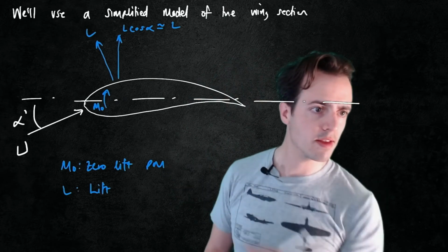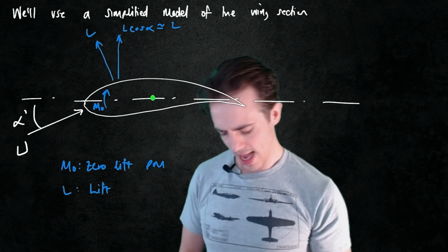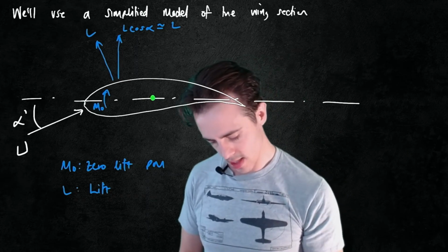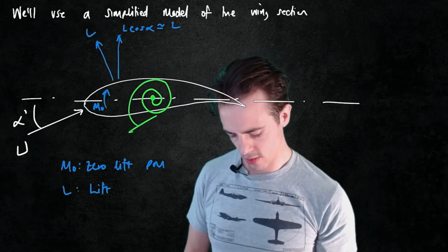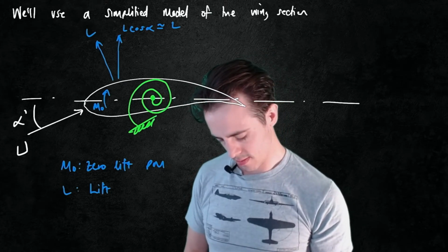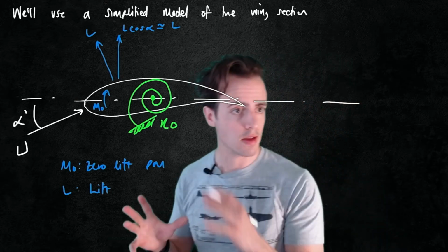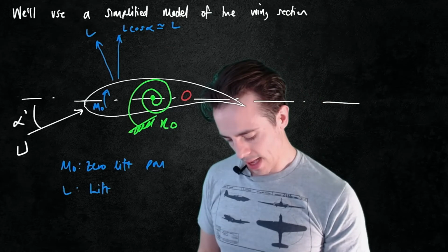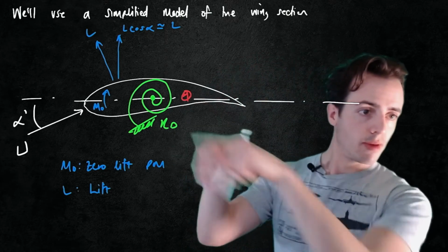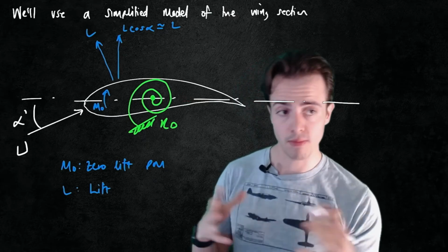Let's draw this in the center. So we can draw this as a torsional spring, which I will call KD because that's what we've used before for this. KD is the torsional spring. We don't actually need to include the mass on here, because this is a static problem, we don't care about where the actual mass is on this aircraft.